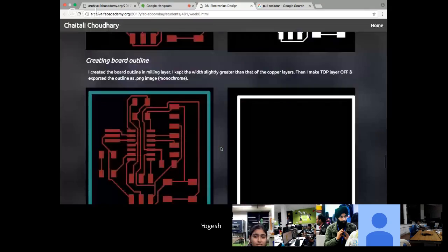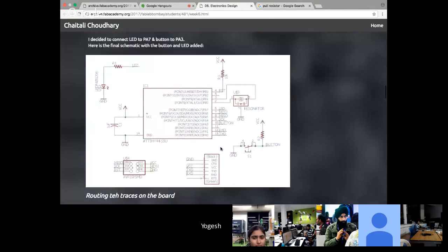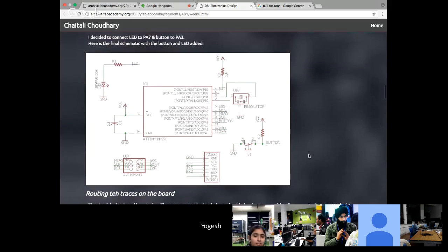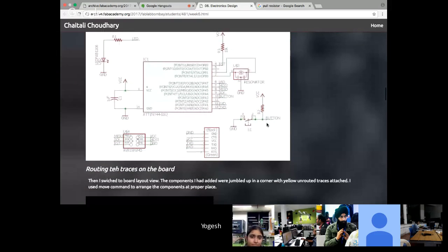So it's very easy to detect pull up. Because when you are not running any program, the pin is directly getting pulled up. So that is a very rough resistance that you can use. You can use almost any resistance of greater value, which will not let a major amount of current flow into the pin when it is grounded. So it is very easy to detect the click of the button, and that is why we use pull up resistors compared to pull down. Okay.